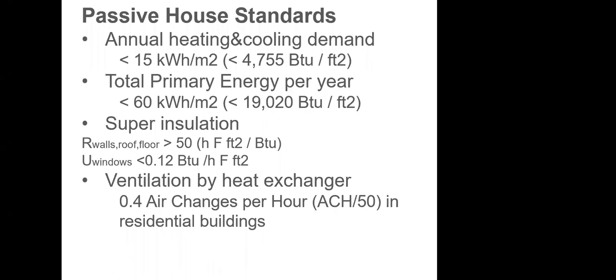Sometimes 10 is enough, depending on the thermal insulation. Sometimes we need 15. So we need something like this of thermal insulation, and then the internal finish and the external finish. But remember that walls are getting thicker if we apply these passive house standards, because the R value should be very high.